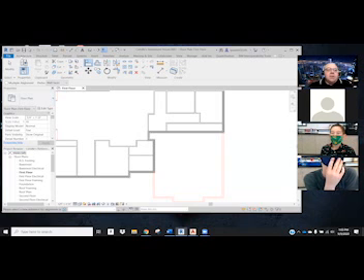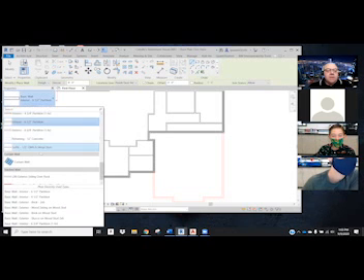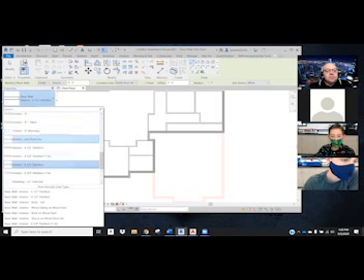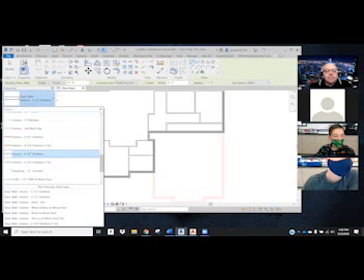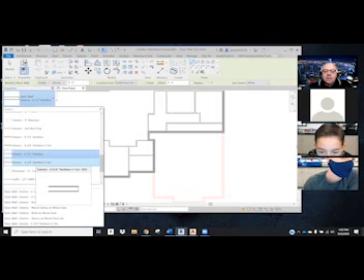All right, so we're gonna do architecture wall. And in my walls, go ahead and find that interior 2x6 partition. Okay, that's where we're gonna start. You actually could use the 3/4, and the difference here is the 3/4, the 1 hour, has 5/8 gypboard on each side of the wall. And that might be a quicker fix for us today to do it that way. So let's do that.